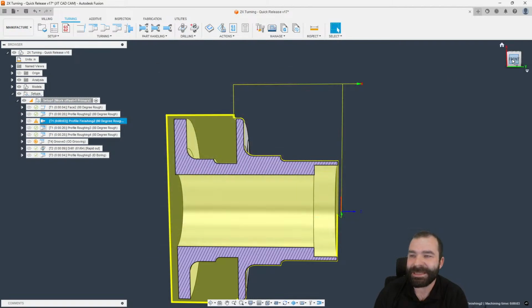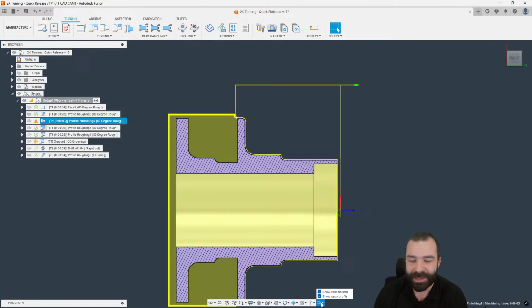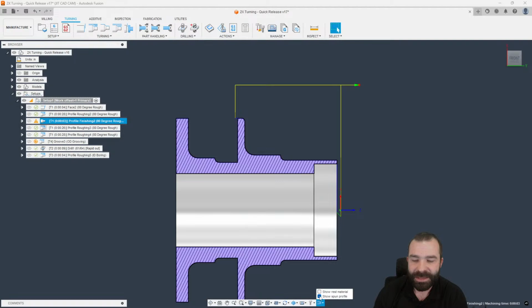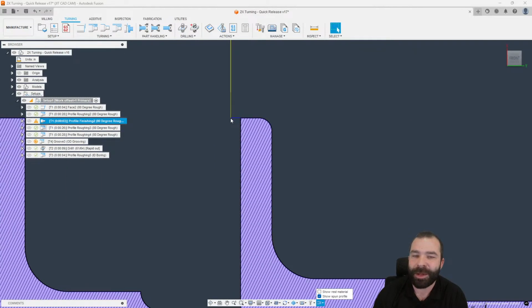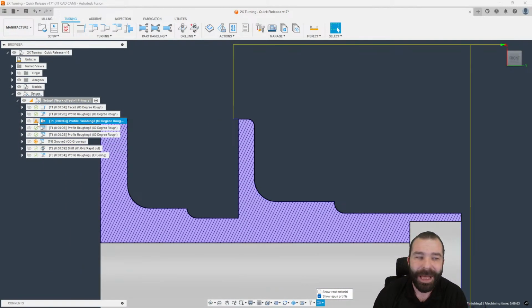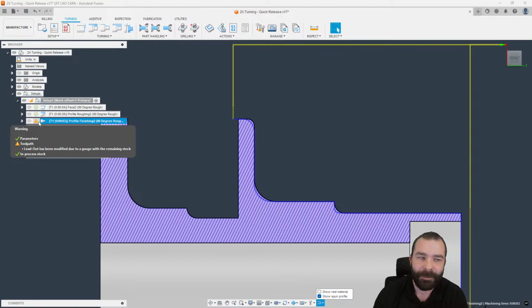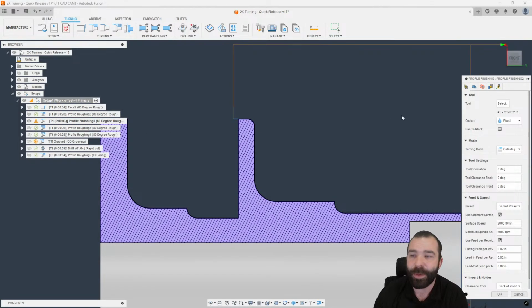So again, this is where we're using the color coding of our toolpath. Let's go ahead and get some stuff out of the way. Our blue line comes up and around, and then we transfer from a feed rate to our rapid or our linking moves. So in order to get rid of that error, we need to modify our lead out. So again, as I go into Fusion, I need to change my yellow line.